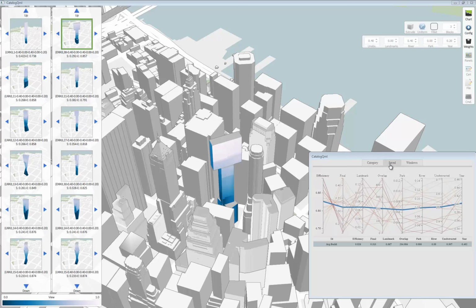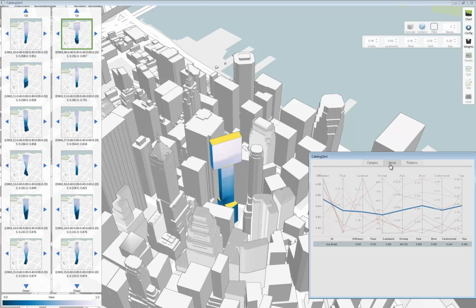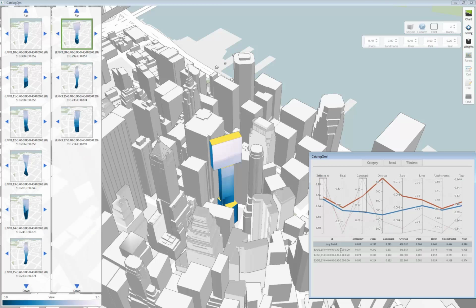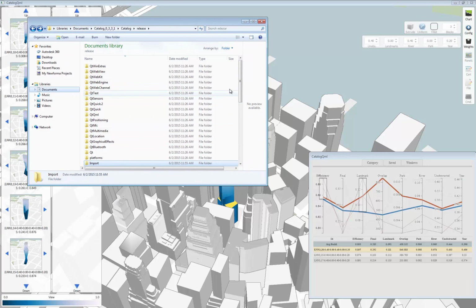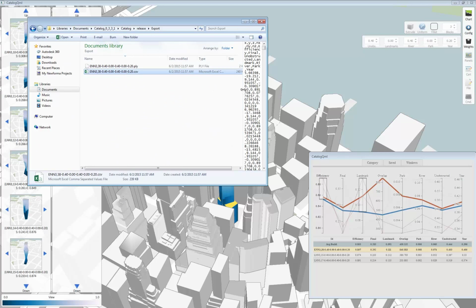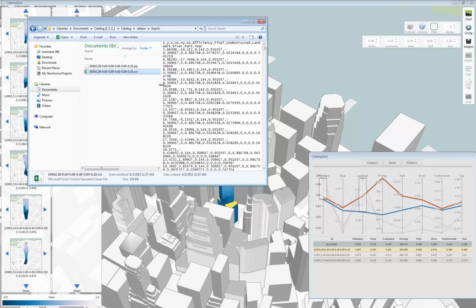The process of selecting spatial features and combined view score weighting can then be repeated to generate another set of high-performing building forms. These can be saved and compared against the previously saved designs. This allows the designer and the client to easily understand the view possibilities for the site relative to the design intent. Once 1 or 2 design massings have been selected, they can be exported as a mesh and a CSV file with associated view data for each window.